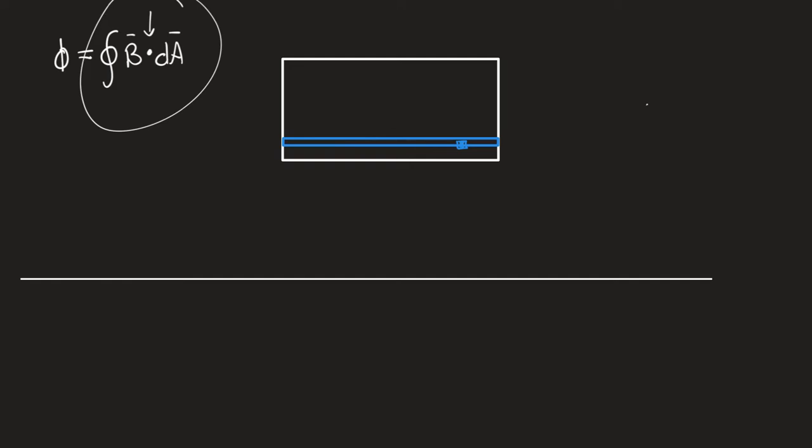And I could do that all across all of those little boxes, but every little box inside here sees a different strength than the one before. So it's important that I understand that it's about how far away I am from the wire, that's the part that's changing. The horizontal part of the rectangle, all those are the same contributions, but the vertical part of that rectangle, that's going to be an issue when I have to sum, and I have to find a way to add it up.